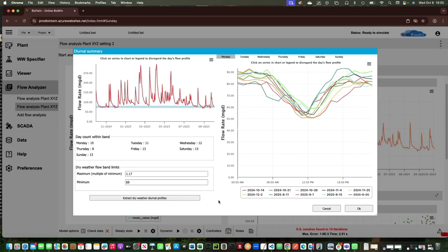So here you can see, because I had auto trim activated for this particular flow analysis, without me clicking on anything, this series has already been hidden from the data set for consideration. If I click on it again, you can see it come back, and it obviously removed this one because this point it detected as an outlier when looking at all of the other trends, so it removed the whole set, right? So I'm just going to click on it again to take it away. So you can always check what it's removed and accept or not accept it.